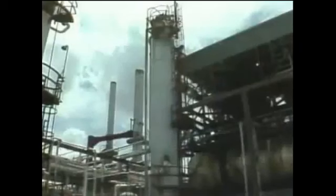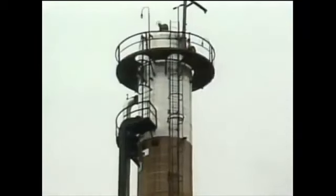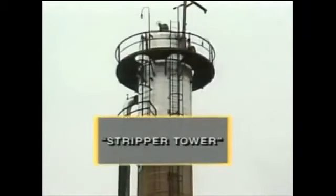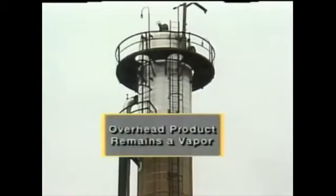For some product specifications, it's necessary to separate light components to control the product's initial boiling point. To meet these specifications, some processes use distillation towers called stabilizers. Another type of tower is called a stripper tower because it strips lighter components out of the products. However, unlike most other distillation systems, a typical stripper tower system does not condense the overhead product into a liquid. Instead, the overhead product remains as a vapor and is sent for further processing.